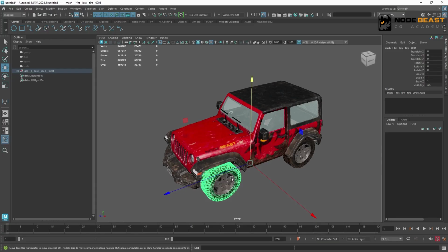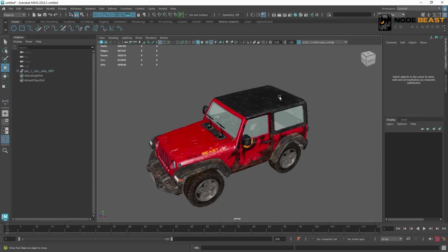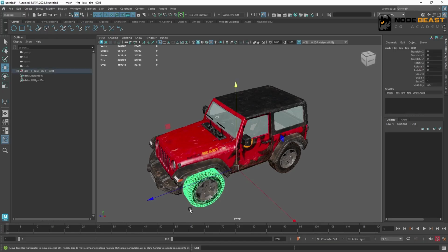Obviously, that's very inefficient. And another reason, speaking of car rigging, we generally write some scripts at work to automate this process. When we run these scripts, it will read the name of each part. It performs the rigging based on its left, center, or right identifier. So if the name is wrong at this point, if I name the left wheel right, then the controller that was supposed to control the right wheel will now end up controlling some functions of the wheel that is on the left. Obviously, this effect is not what we want, so we must be careful here.